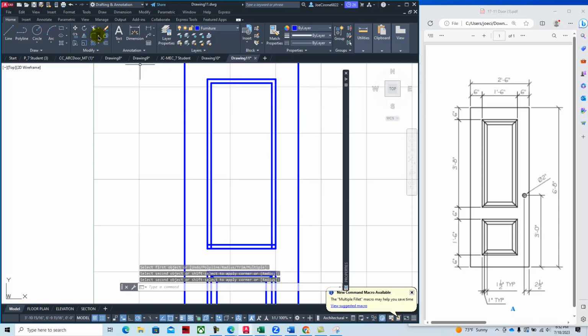And when I talk about fillet multi, when you go to fillet, one of the options here is multiple. And so when you say multiple, you don't have to go back and retrieve the command every time you use it. Offset 1-1/2, 1.5 inches. You don't need to put the inch mark, but you can put it in if you like. And then the command will work.